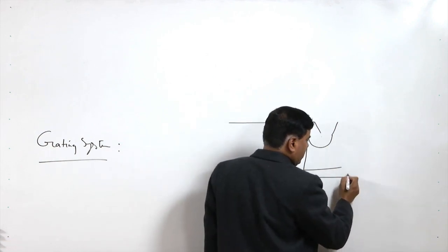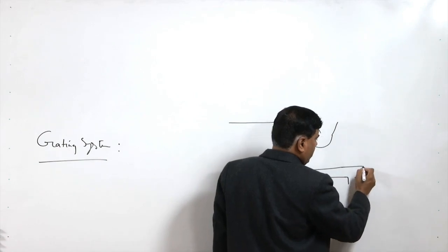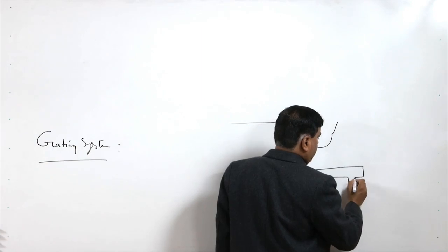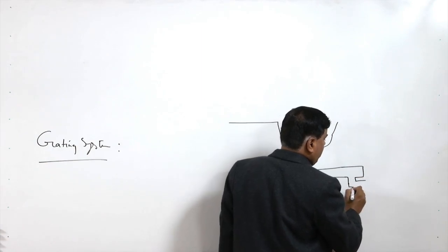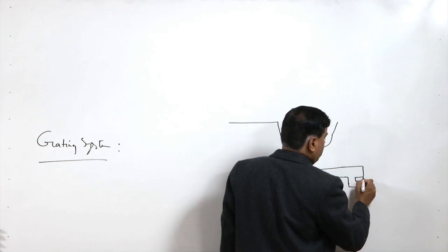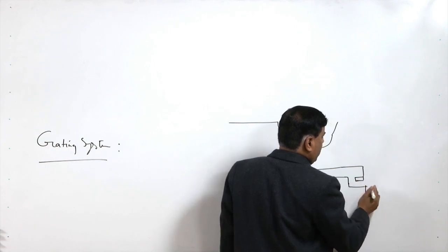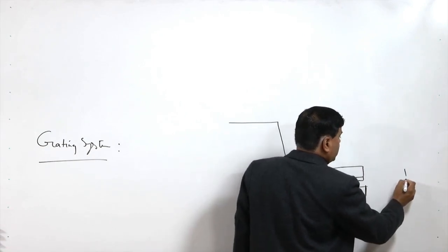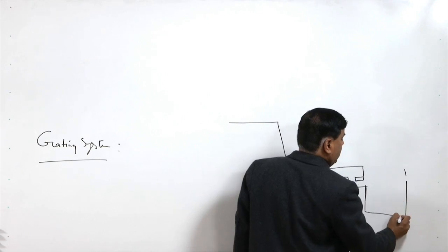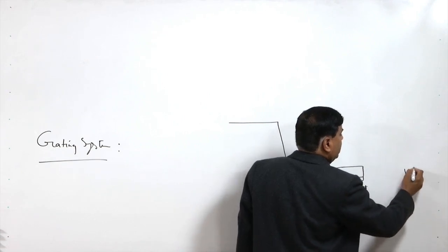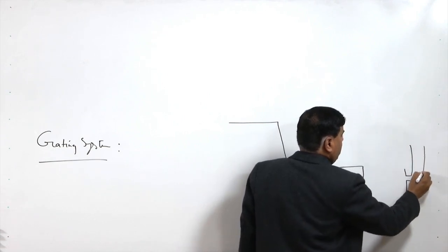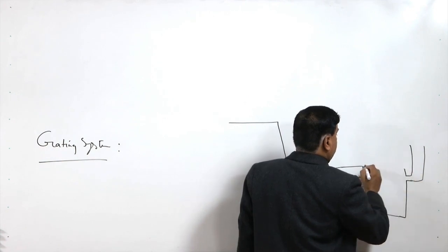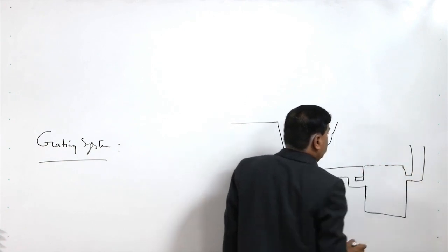This is the mold, this is where the extension is, and this is where we have the mold cavity, and this is the cavity. In this case we may have the riser here. So, metal enters and then goes up in this manner.